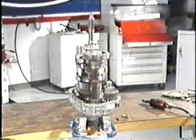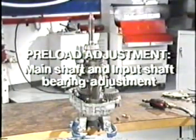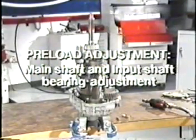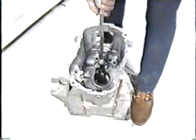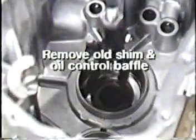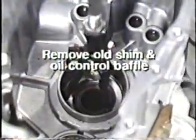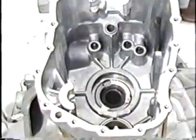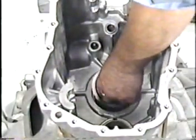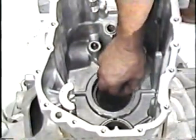Let's walk through a preload adjustment on the main and input shaft of a S542ZF transmission. Remember, this is just an example. Each and every transmission and transaxle is different. In many cases, the first step is to remove the old shim so that you can get a baseline measurement. It may be necessary to use a slide hammer and puller to remove the counter shaft and input shaft tapered roller bearing outer races. In some transmissions, an oil control baffle is used that will also be removed. The baffle will be destroyed in the removal process, but the shims are reusable.